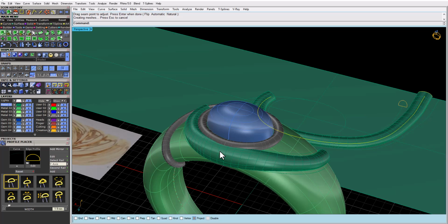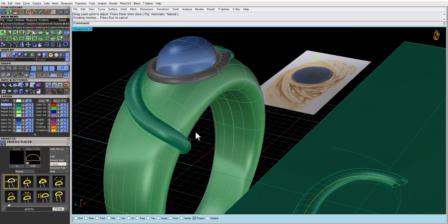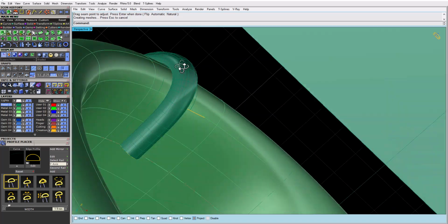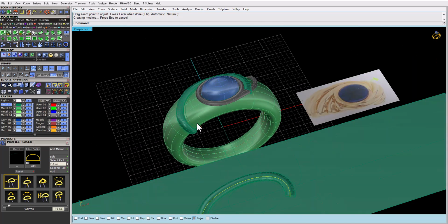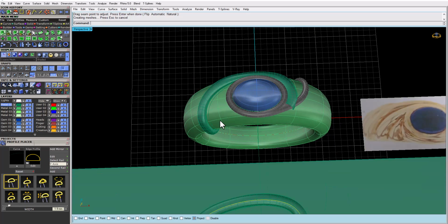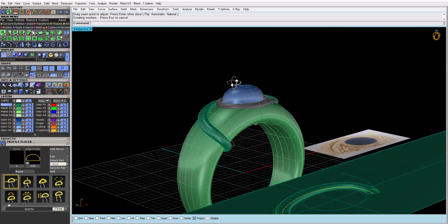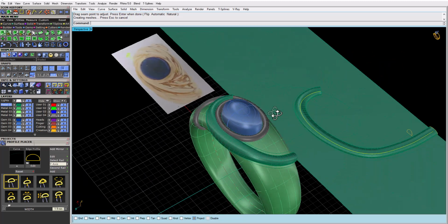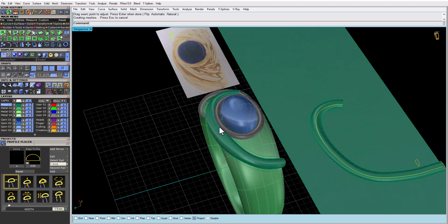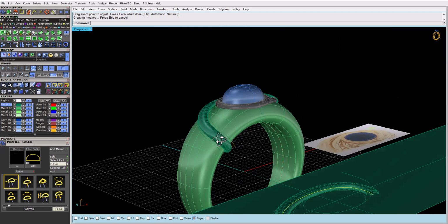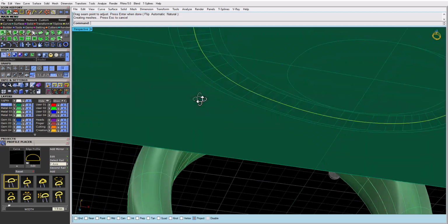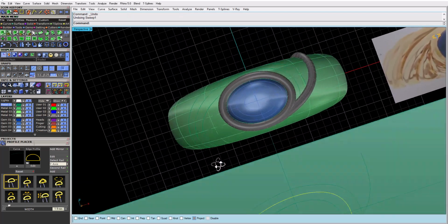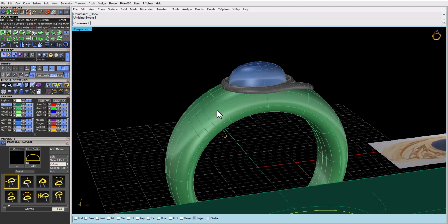So as we can see here, this is more fat over here, and then here it's a bit thin. Okay, so this is the problem. That's the only reason I did an offset curve on surface, just to make sure that I have proper thickness. So what we can do here, instead of doing things on the base surface, let's just take the profile placer here on top, and then you can do it manually.